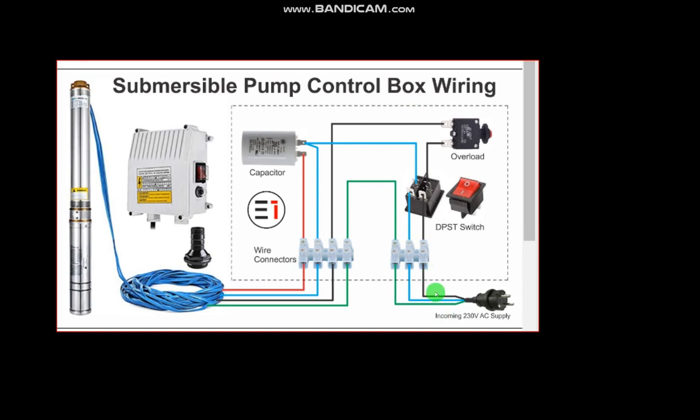This is my supply. Okay. This black conductor is our live conductor. Please take note. We have changed the wiring color code. Color code is no longer bearing neutral for live neutral conductor. Our live conductor is now black for line 2. All right. Line 1 is brown. Line 2 is black. Line 3 is gray. Then neutral is blue. So when you see this black is not neutral, please. Neutral is blue. That is this one.